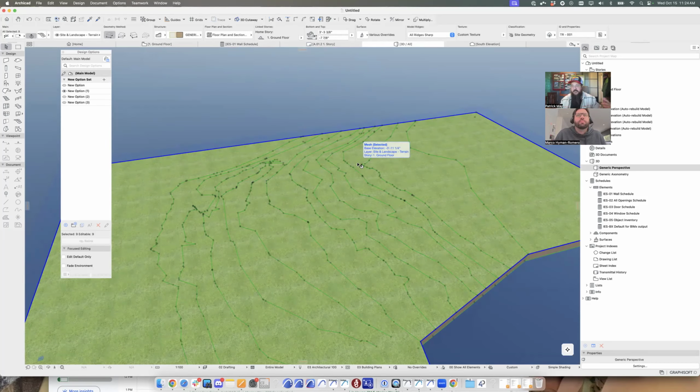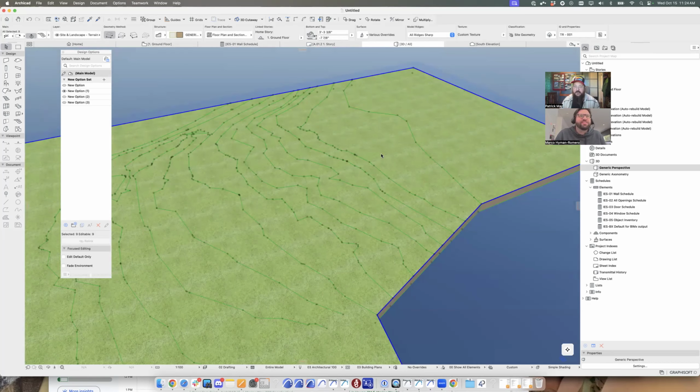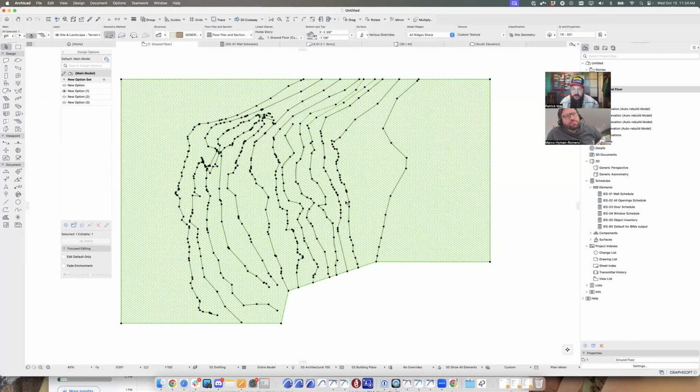On a site of 250, 300 acres with thousands and thousands of contours, it was really hard to figure out where those were. In the end, I had to throw the whole thing out and redo the 6 hours of work. So, lesson learned, even on a small site, elevate 5 or 6 contours and check it in 3D. Go back to 2D, elevate 3, 4 or 5 contours, check it in 3D. That one 15-second check will save you hours of headache trying to reverse what you had done.